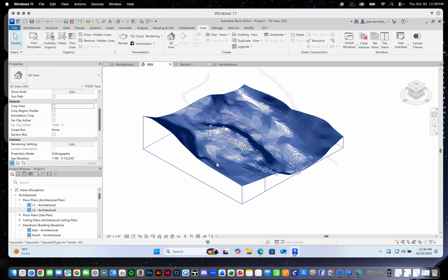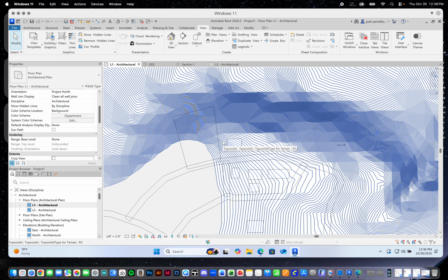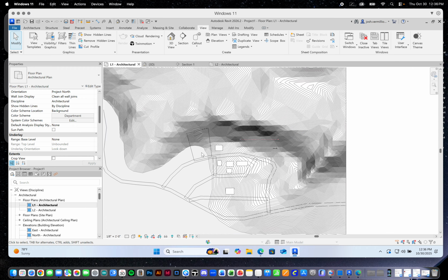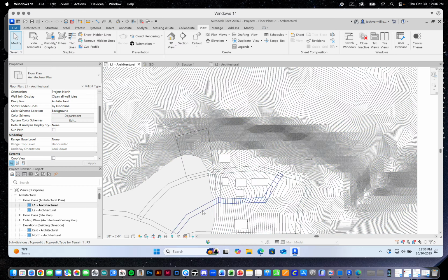All right. So let's go to level 1. And just like in section and elevation views, the side views, we can see where those elevation markers are for our floor plans. In floor plan, we can actually set the section cut markers to start to generate more sections. So one of the things I'm going to do is cut a north-south section through my